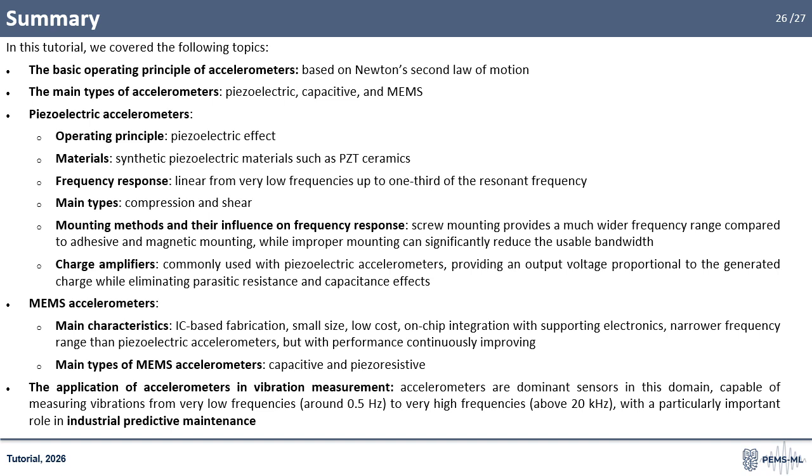Finally, we discussed the use of accelerometers in vibration measurement. These sensors dominate this field, enabling measurements from very low frequencies around 0.5 Hz to high frequencies above 20 kHz, and they play a key role in industrial predictive maintenance.